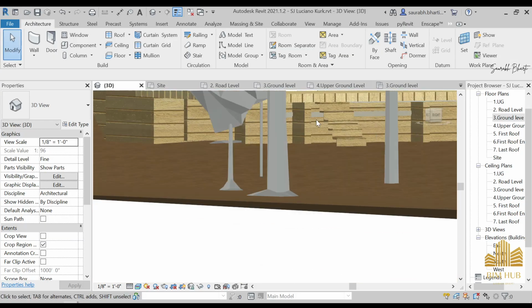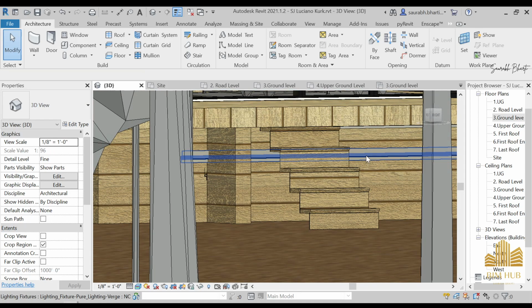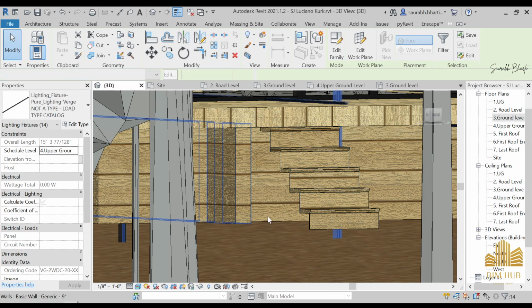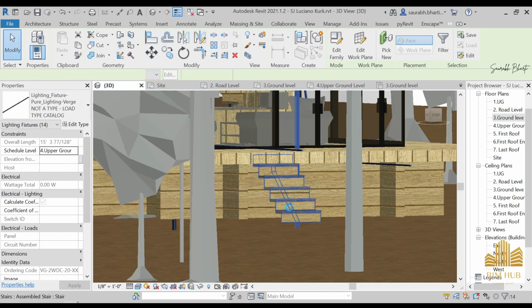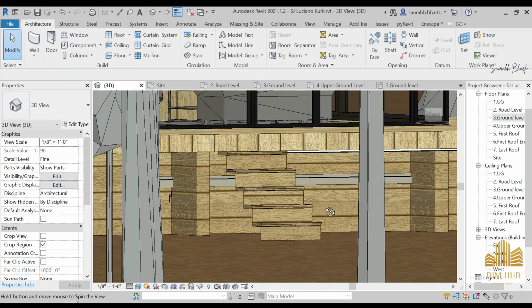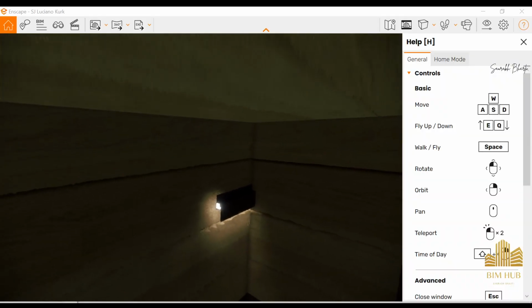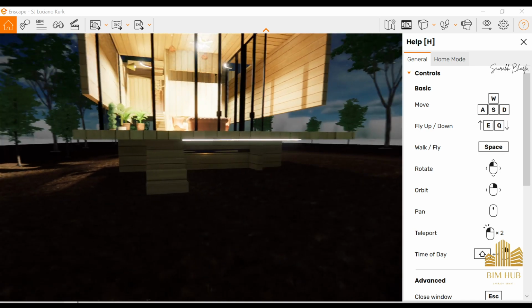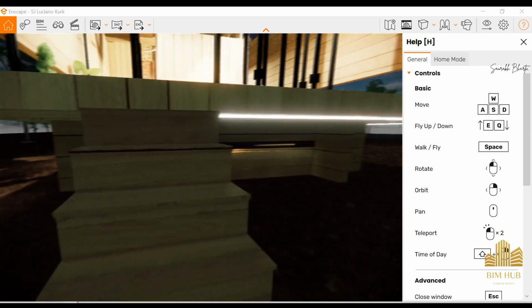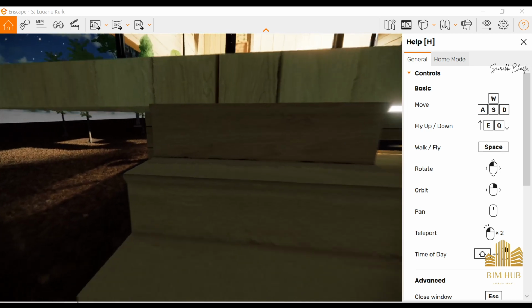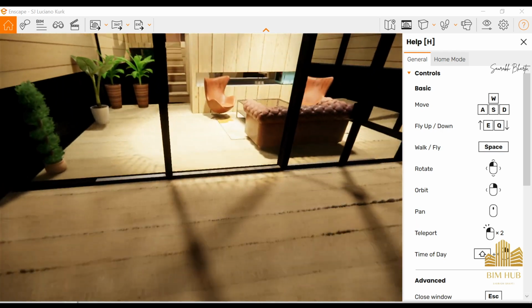Just select everything at once, just select this one, and SA is this shortcut, and then press escape, and not escape, space, so space bar, and now press it twice, and now I can see that it is on this face, but there's something wrong. It's still on the wrong side. So okay, we will fix that. Okay, this looks good. You can see that lighting from the outside, and this is where we can start.